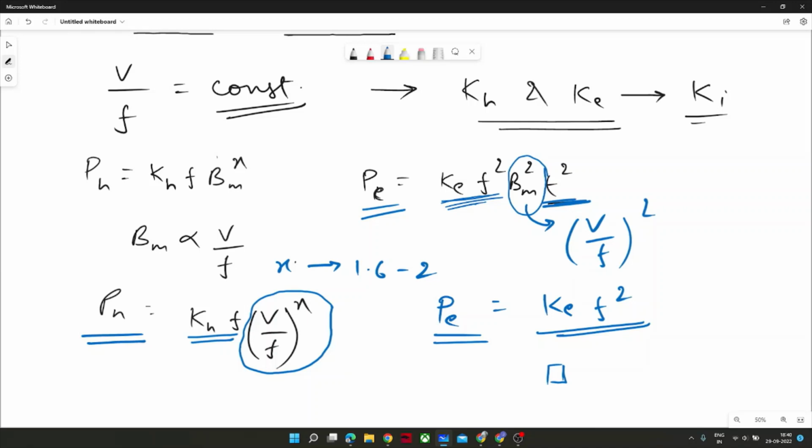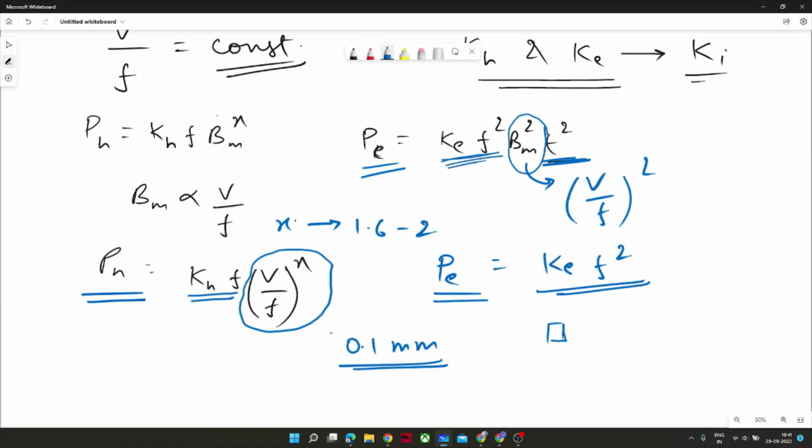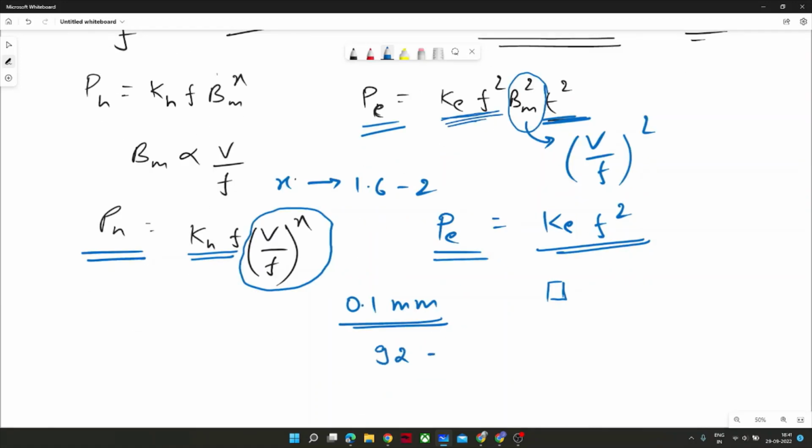But nowadays, since very high power, very compact motors and drivetrains are required, the minimum lamination steel thickness I have seen till date is 0.1 mm. And believe me, if I design a motor for 500 or 600 kilowatt, it improves the efficiency from 92% to 97%. 5% of efficiency in terms of hundreds of kilowatts is significant.